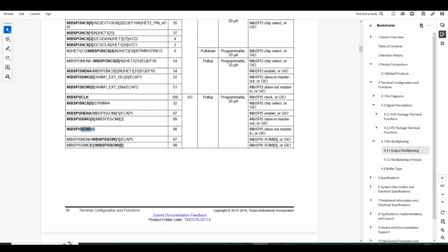And actually if you look in the documentation generally for SPI peripherals, you'll see that the reason they have multiple inputs and multiple outputs is so that you can operate the SPI in a parallel mode. So whereas one clock might clock out, let's say 4 bits on 4 SOMI signals, so you could do quad SPI for example. We're not doing that, and it's again also worth noting that SPI 5 does not provide you with many of those signals, so your options would be quite limited there.